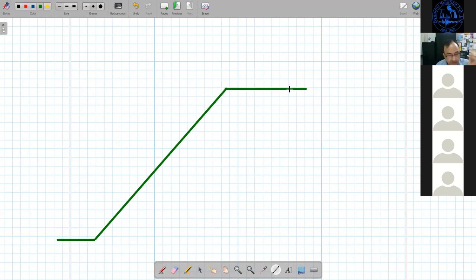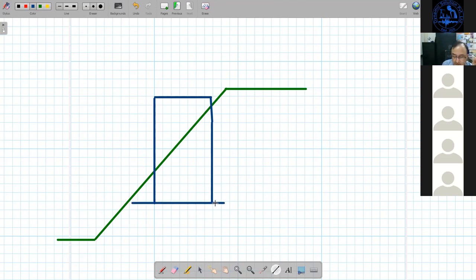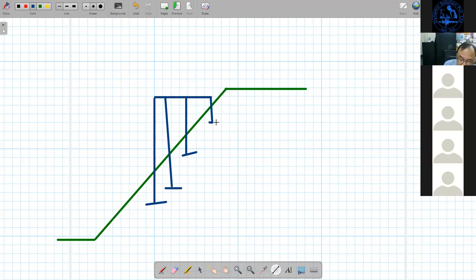Yes, this is one of the areas where we are working currently. This is my favorite area: earthquake engineering in hilly regions. So when you are constructing a building on a hill, the code says that you construct the building like this. But is it possible to construct a building like this on a hill? It is not possible. So what we actually do is provide our columns at different levels.